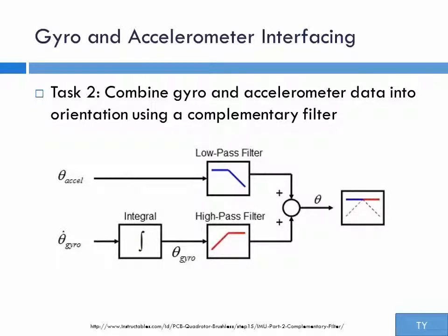The gyro measures the angular velocity in degrees per second. Integration is constantly performed at each sample point in order to obtain the degree value. But this degree value tends to drift over time because the noise is accumulated with degradation. So the gyro's reading is only accurate for a short time.